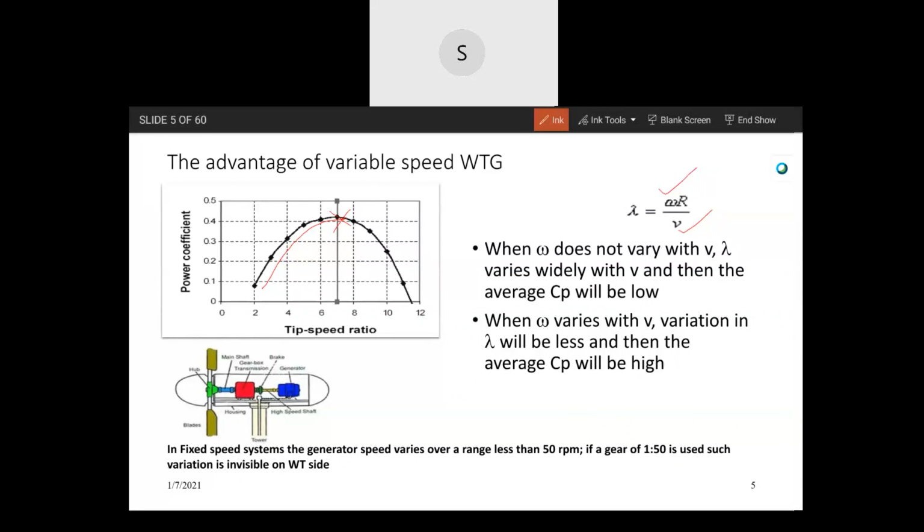So usually, the electric generator is rigid regarding its speed, and when coupled with the turbine, the generator decides the speed or the range of speed. For that reason, varying omega with the wind speed proportionately is not an easy task. Which generator, and to what extent this can be done, we can discuss later.